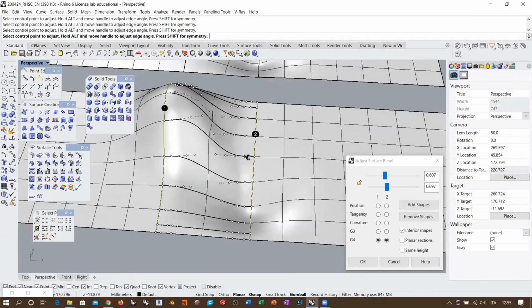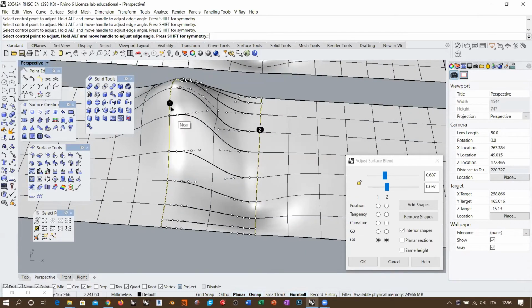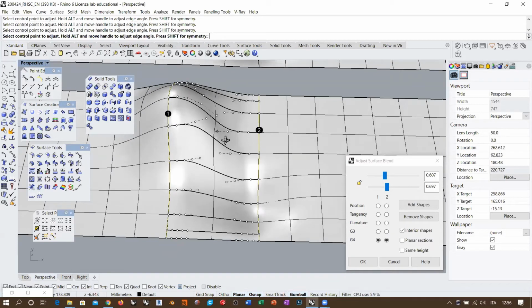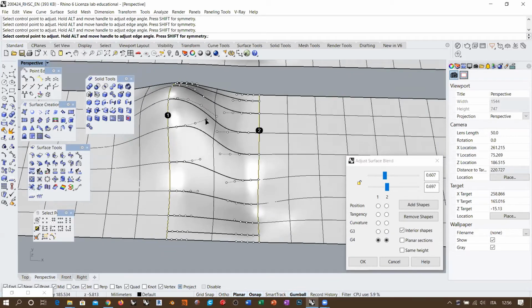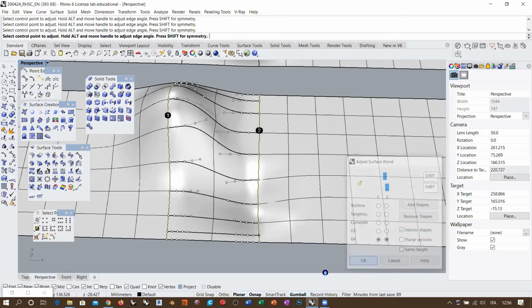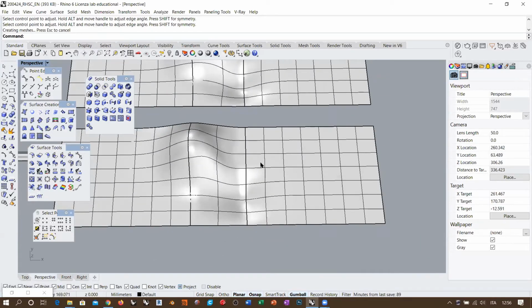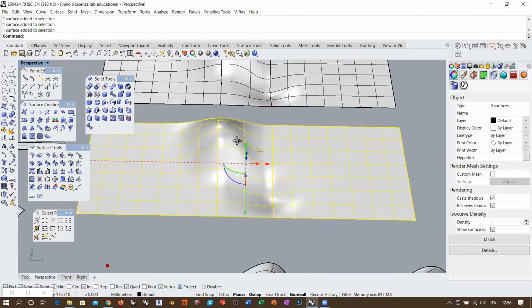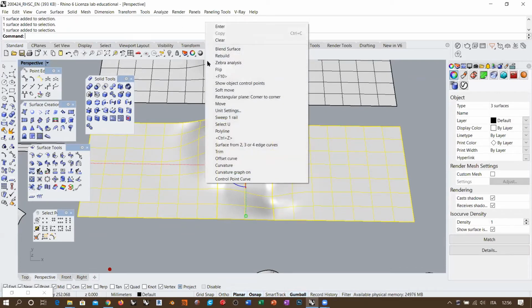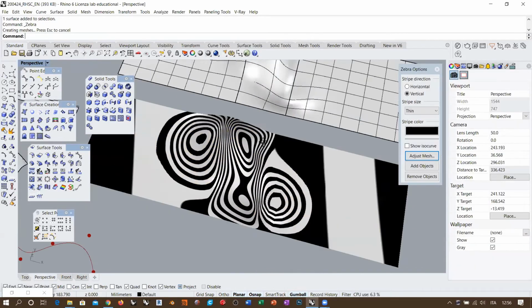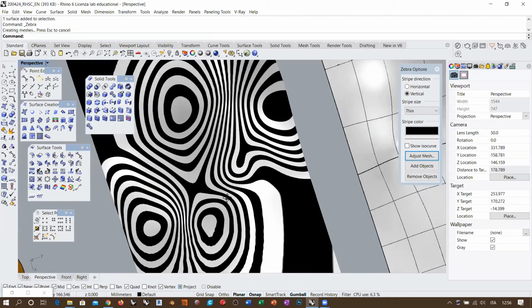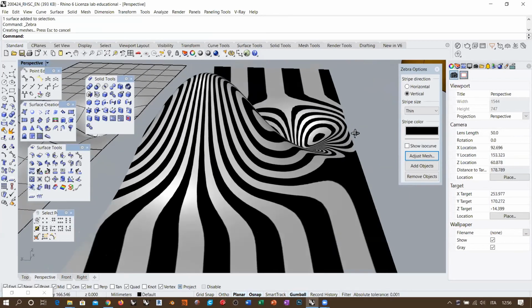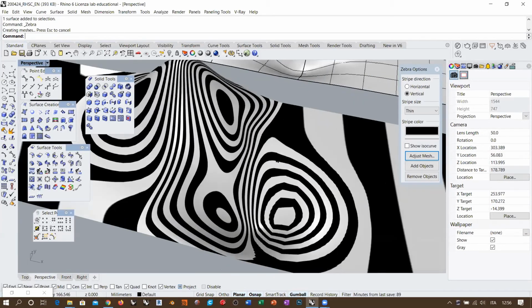So if I do this, I have an extremely continuous relation along 1 and 2, right? But I have 1, 2, 3, 4, 5, 6, 7, 8, 9, 10 control points in this direction, okay? So, of course, I get perfect, smooth geometric continuity between these surfaces. You see, there is absolutely no possibility that some break appears along these stripes, right?